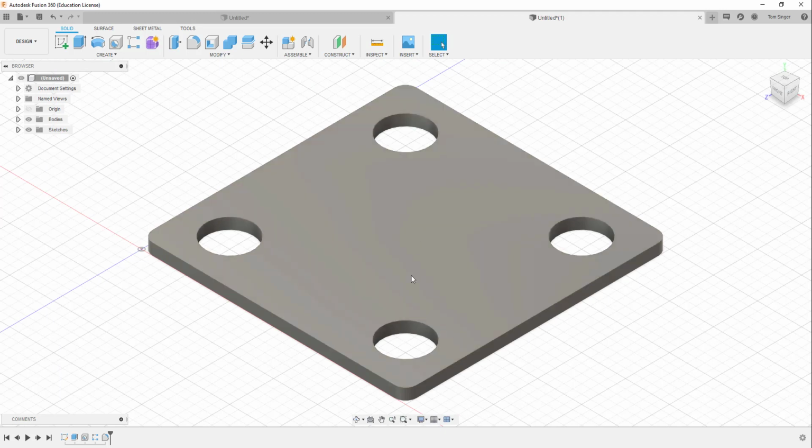All right, so with that being known, what we're going to do is work on the shape. So we have to, oh, by the way, this is now an object. It's called a body. If we want to assemble multiple pieces onto this body, or if we want to create multiple objects for an assembly, we have to change the body to a component. And this gets a little tricky because this particular plate would be created. The verticals would be welded in place, more than likely. They wouldn't be part of the plate itself. They would actually be welded in place, so they'd be a separate object.